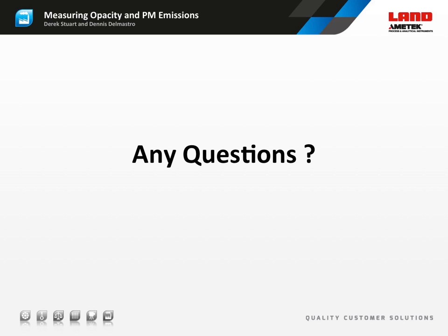Another question for you. What is a manufacturer's certificate of conformance? It is a comprehensive booklet issued by the manufacturer to the end user that the opacity monitor is certified. This document, also known as the Blue Book, contains the test results of the per unit, quarterly, and annual validation tests, which prove that the opacity unit met the design and performance test criteria and successfully passed the field audit tests.